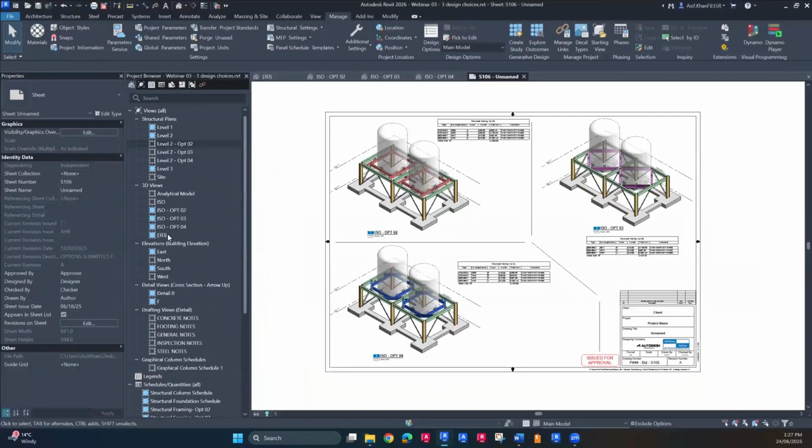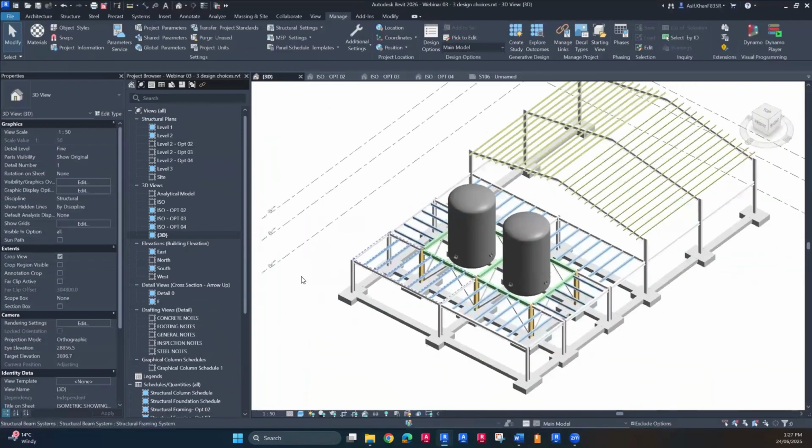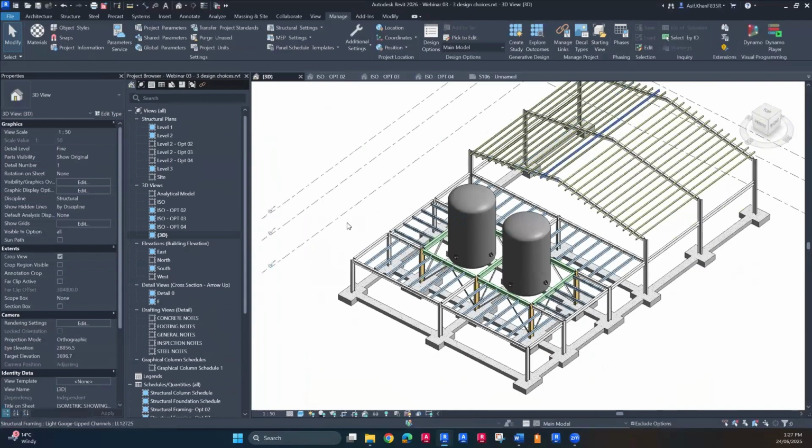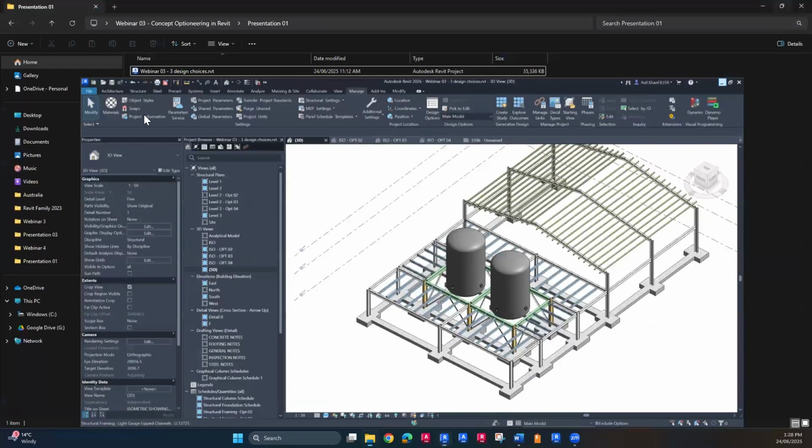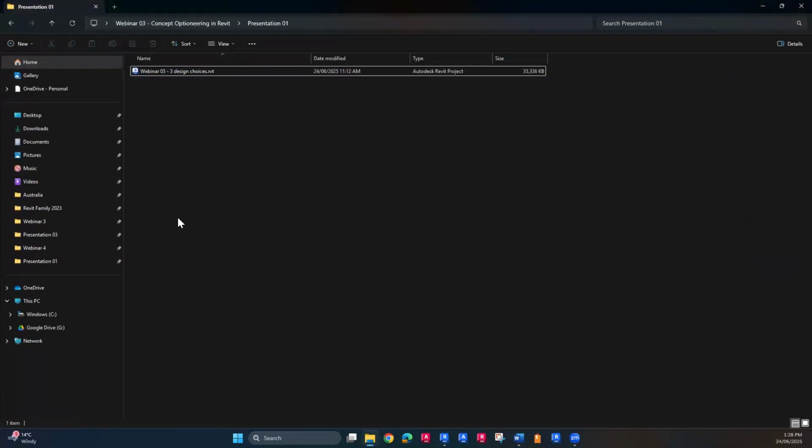When I say base model, it's basically the rest of the model I'm talking about. When the base model changes, such as member size change, member orientation change, plus grid line shifted left, right, up and down on the plan view, in that case, you have to do all the changes to all 6 design options.